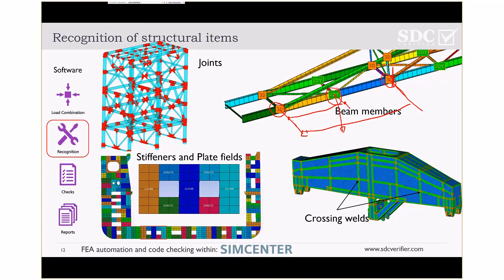And then the user has to take care for himself that the buckling length, in this case in the vertical plane, is the double length. If you forget to do that, your results are 4 times off, because the buckling risk goes with the square of the length. And so it's extremely important that you recognize all these things together. So this is one thing we recognize.